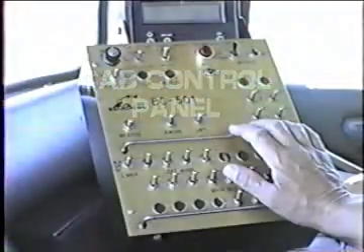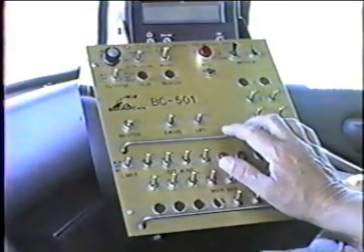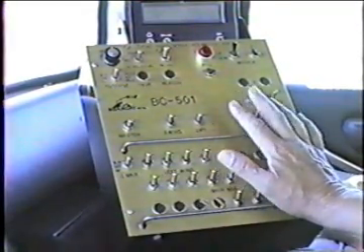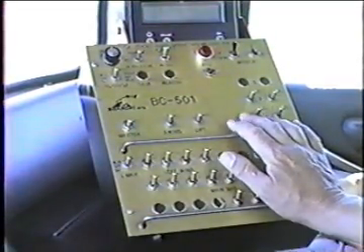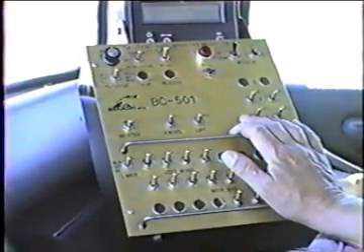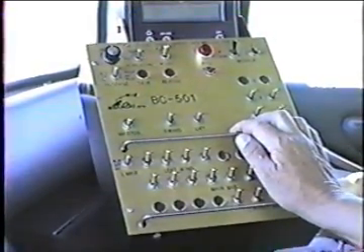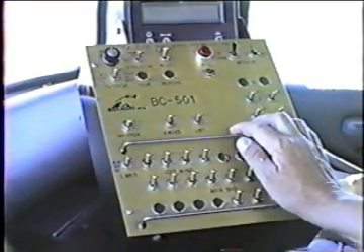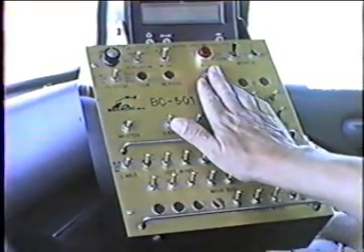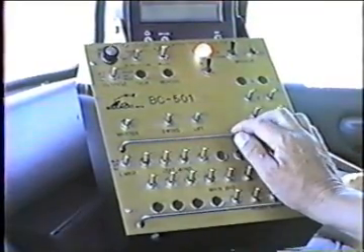This is the control panel for the 501 Bearcat spreader. Going over the panel, of course, the very first thing that you would ever do when you come to the job with the truck is to put the power takeoff in gear. Just a rule of thumb, when you get to the job, put the power takeoff in gear. When you're all done, ready to go home, take it out of gear. Push the clutch in, put the switch up, and the PTO goes into gear.